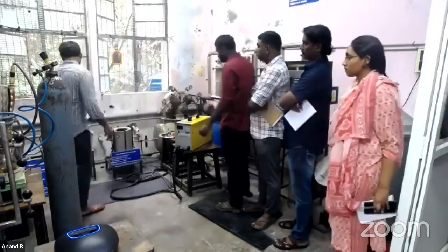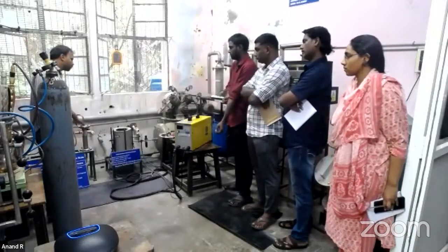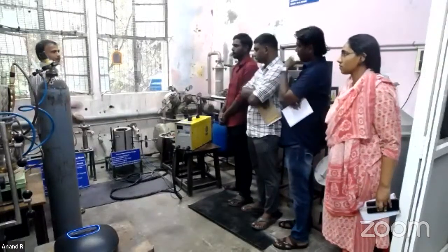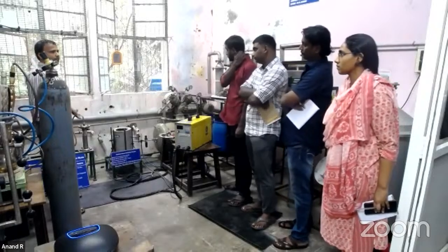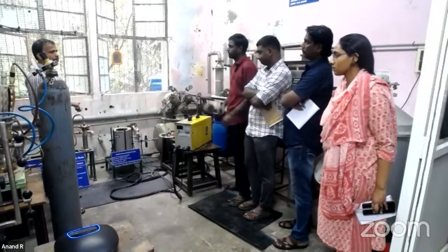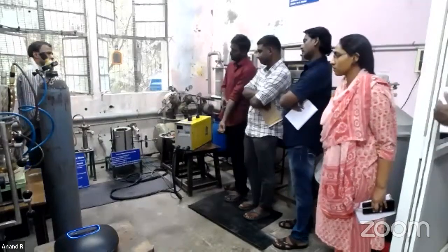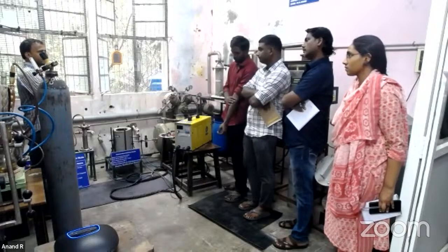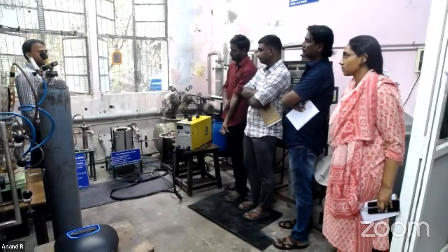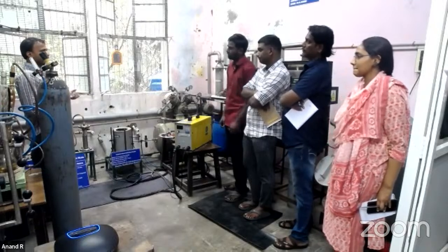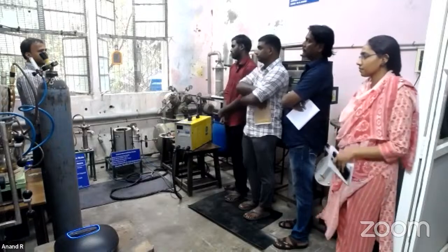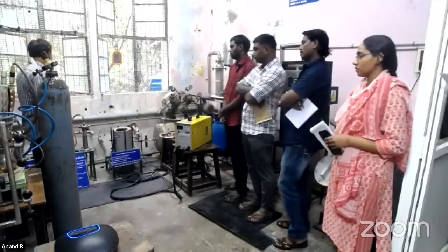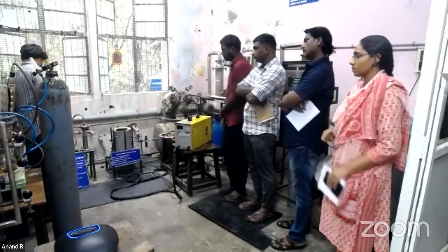Before moving to that, here you can see 3 chambers. The first one is the cyclone separator. The cyclone separator helps to separate particles by density difference, so the heavy particles are strained out here. Then the second one is the wet scrubber. In the wet scrubber, we are scrubbing pollutants like HCl. You can use any wet scrubber solution, or else water may be used. So water may drain the nano-sized soot. Here heavy particles are collected, and the syngas is completely cleaned.